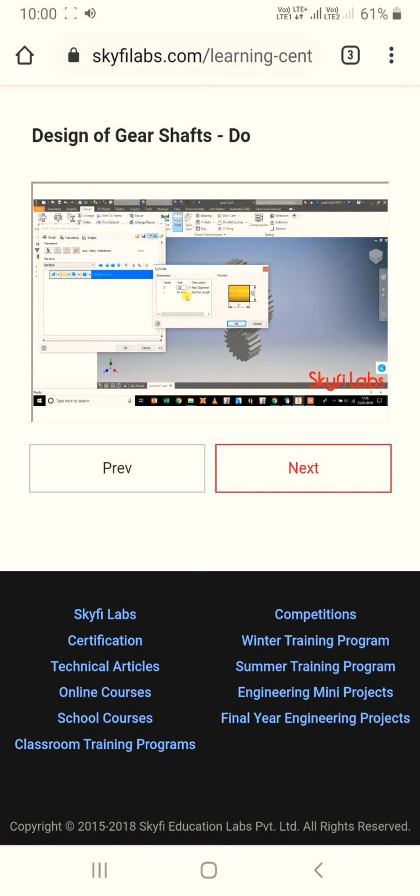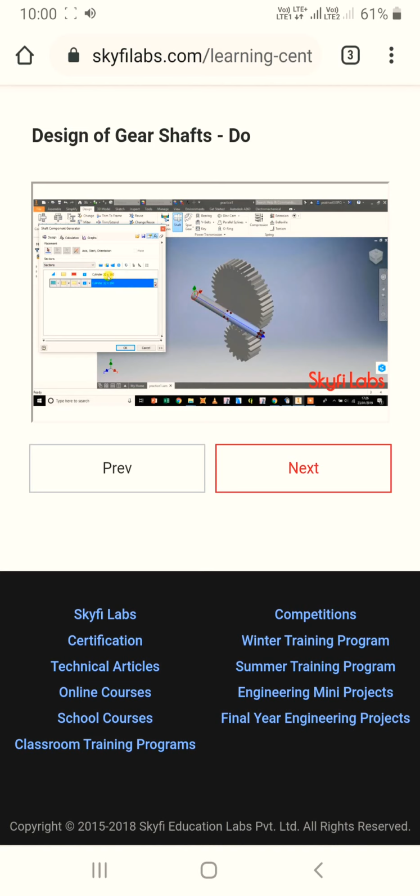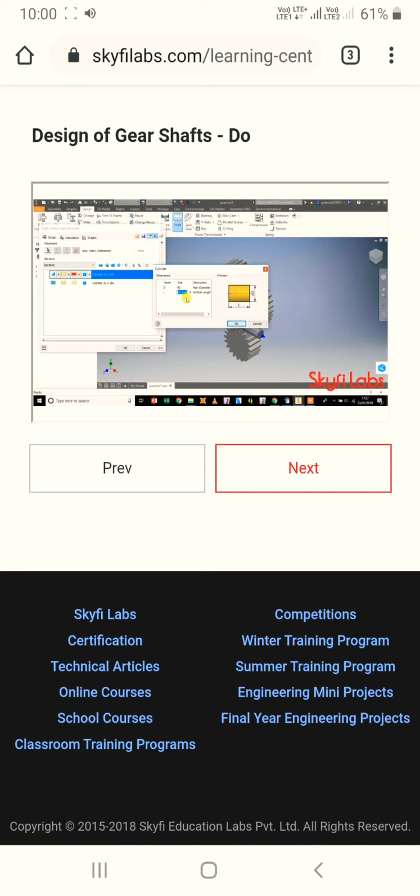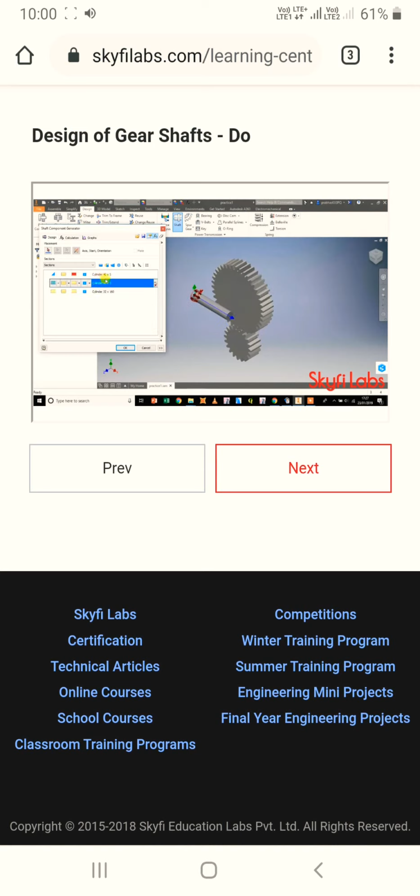Each section will be created by giving the diameter and the length of the section as the inputs. We can also define the edge features, the section type, and the section features by selecting the appropriate options. Now, create a shaft with 5 sections, with the shown dimensions, and no features.